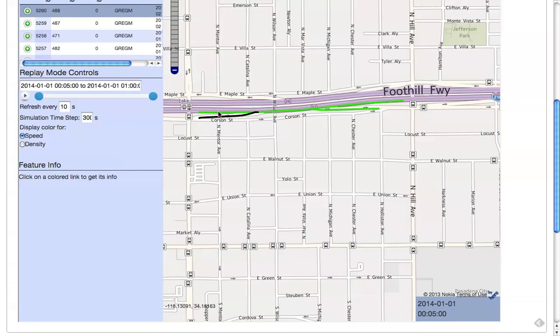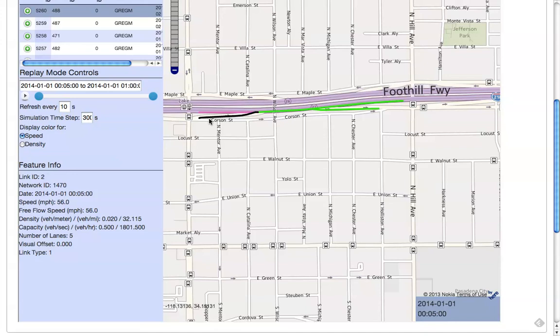So you can see, for example, here on the main line, we can see the densities and speeds. The ramp, the speed is effectively 0 because I've flooded it with an unrealistic amount of vehicles. You can also look at where we have this diverge. You can see 0.038 or about 0.04 vehicles per meter. And we can see about 1/10 of that on the off-ramp. That corresponds to our split ratio. And that completes our demonstration.